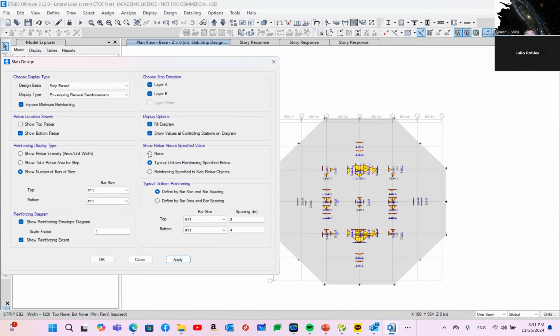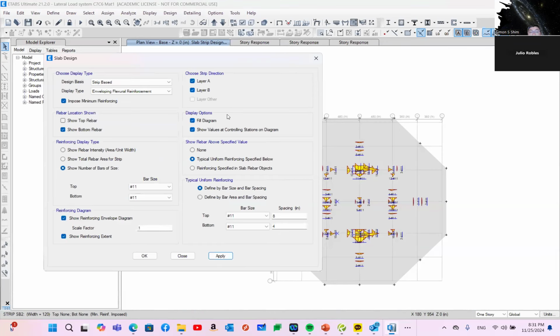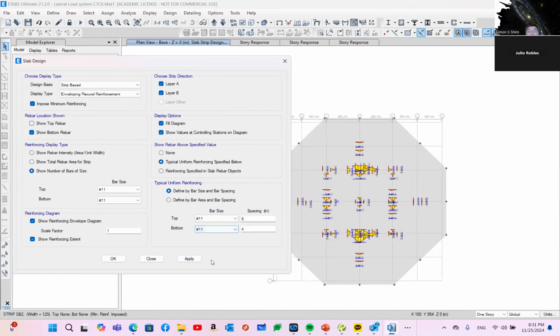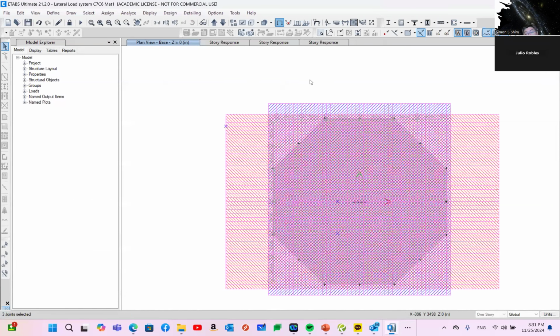All right. So this is a tool you just use, because ETABS already calculates the required rebar areas. Now it's engineer judgment which bar you're going to use. You're going to bundle it, use closer space or wider space, but the bottom bar and top bar you can turn on and off and summarize, so that you propose what number of bar you're going to use for the bottom bar and top bar. Okay, I think that's it.